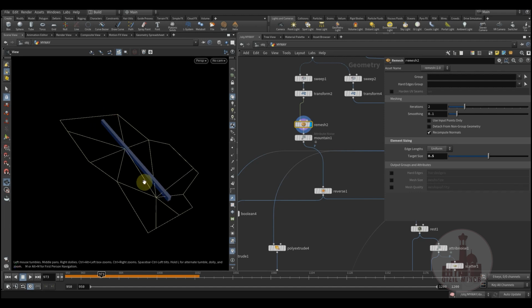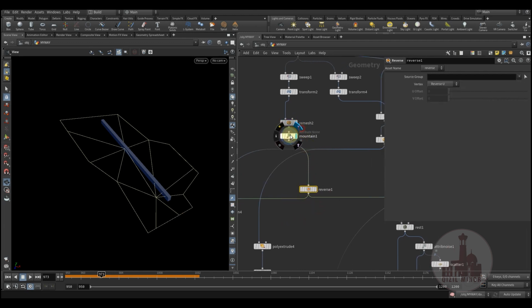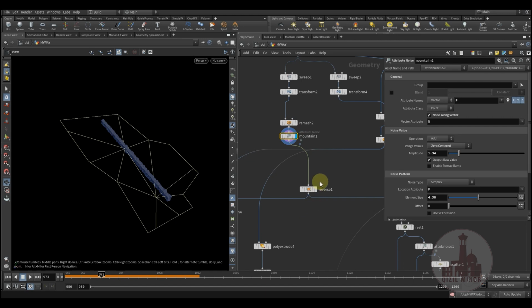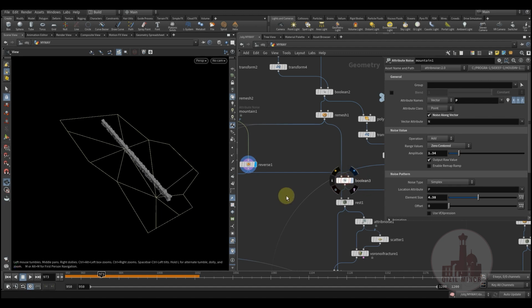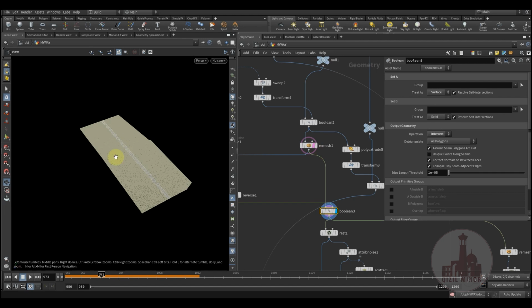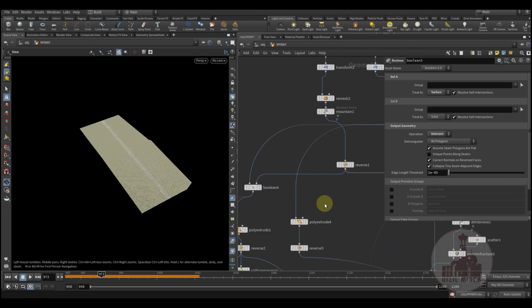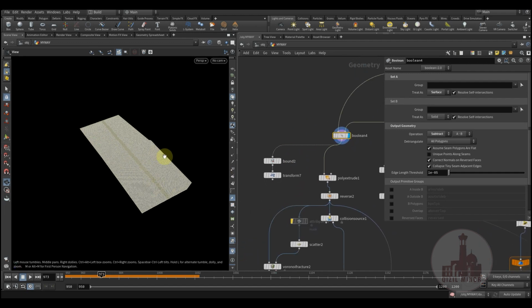So this piece will be broken into pieces. Now, this is the area where the worm is crawling, and here I'm reversing it. I'm adding some noise just for having some irregular shape, and then I'm cutting this out from that final ground piece. And here I'm doing some setups for the rest of the ground that I will use as a collision